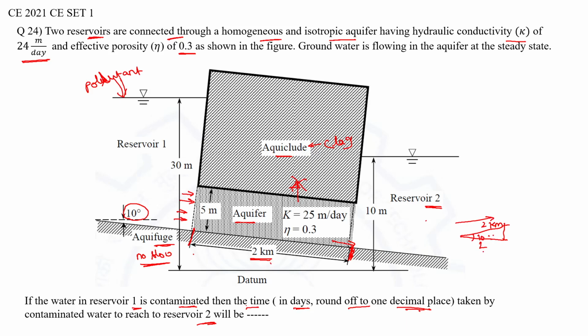One may compute this side by using trigonometry. That is not at all necessary, because the flow is traveling 2 kilometers. It is not only traveling the cross sectional distance, it is traveling the whole 2 kilometer distance. So the delta L should be 2 kilometers, or 2000 meters.